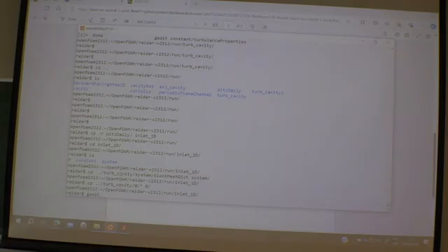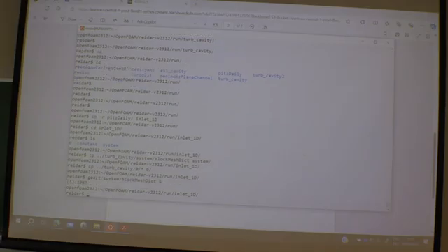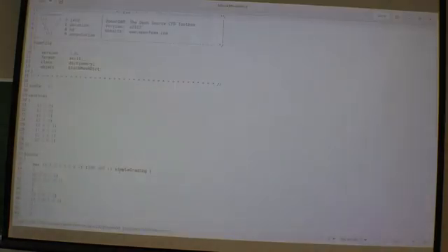gedit, and then we had system blockMeshDict. So here we have the mesh. Here I have used 1 by 1 meters and then 10 centimeters in the Z direction. Yeah, why not? We can keep that one. And then I had 100 by 100 cells. Now I want this one to be a one-dimensional case.